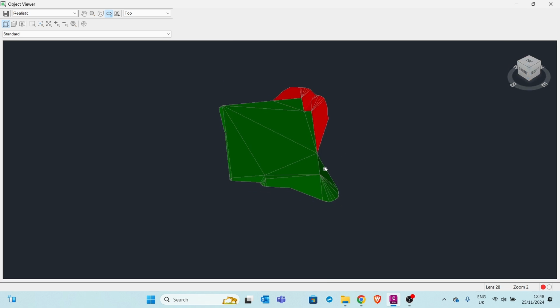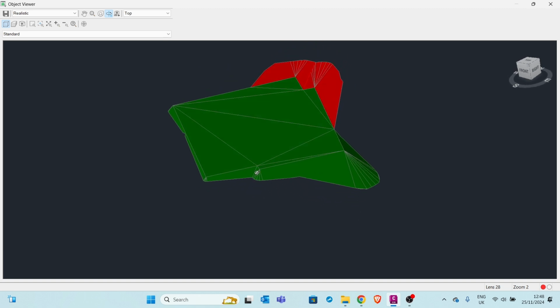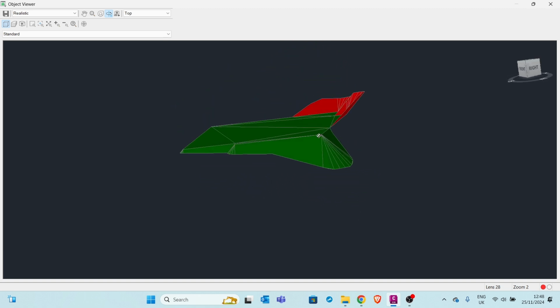As you can see, there you go. We have our cut there that is very sharp, and then we have our fill on this other side, and then maybe our building will be flat, and we know what to perform on this cut. If you want to do a retaining wall that will retain the overburden that is on this side, we can also do that.